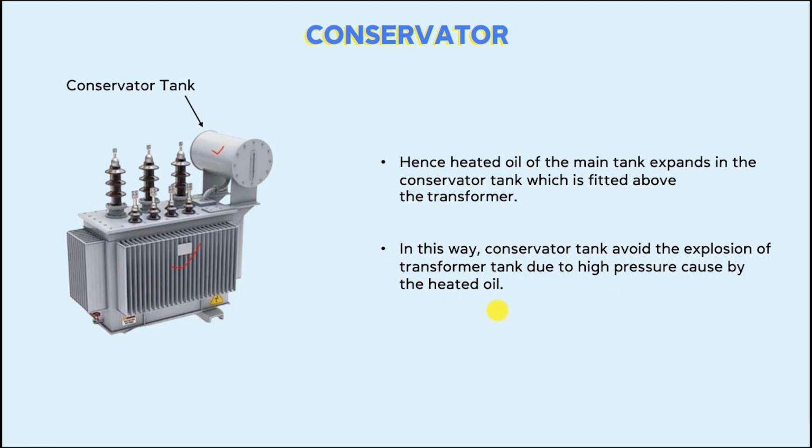So when the transformer oil gets heated, there are chances that due to the high pressure caused by the oil, the transformer tank may explode. In that scenario, the conservator provides a space to the heated oil so that it can expand and avoid the explosion of the transformer tank.